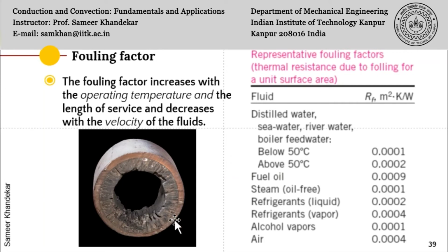And if the pump is not capable, then the mass flow rate gets reduced. And if the mass flow rate gets reduced, the Reynolds number gets reduced. The Reynolds number may change if the pumping power is not increased, and therefore the heat transfer again gets dropped. So not only does the h_o get affected, there is an additional conductive resistance also because of this fouling.